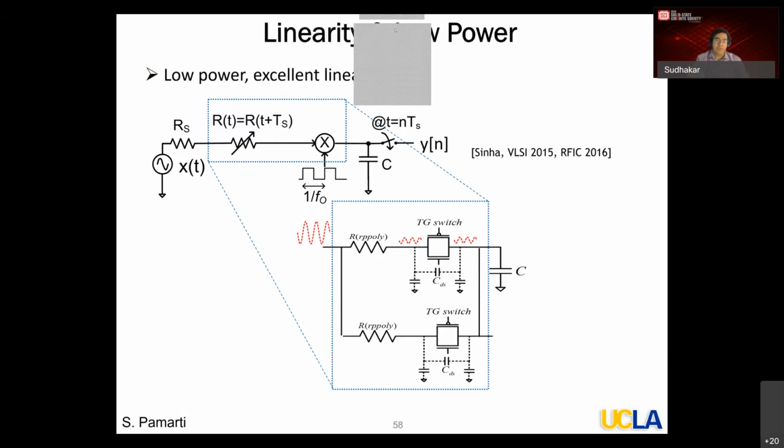So they will have some impact on the S11, right? That's more of an LTI kind of calculation, but it can present more and more capacitance as I go to higher and higher LO frequencies. But that is not that different from any of the NPAT or the mixed plus kind of approaches either, right? So that is where it stands. So I believe it should be possible to apply this to situations where the LO frequencies are higher. You may have to do some modifications. But if you want higher bandwidths without changing the clock frequency or the switching clock frequency, that could be trickier.